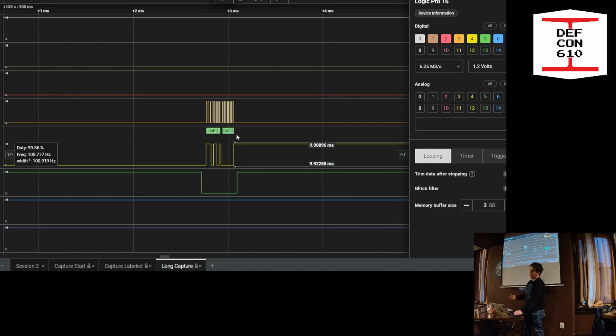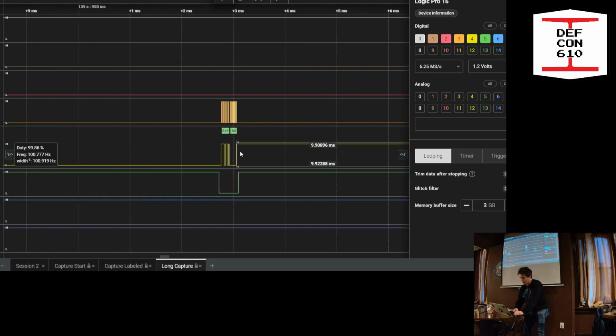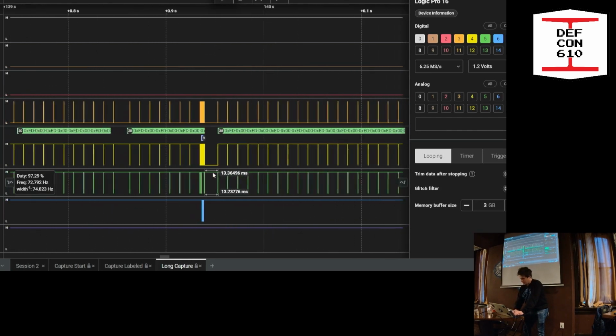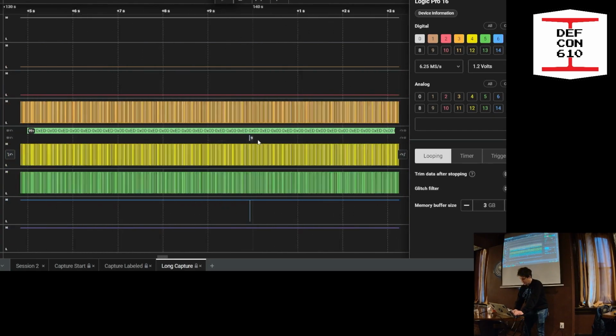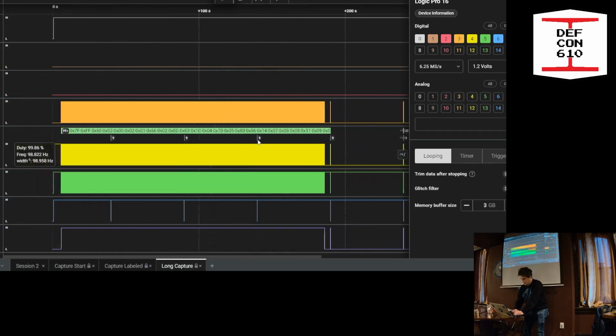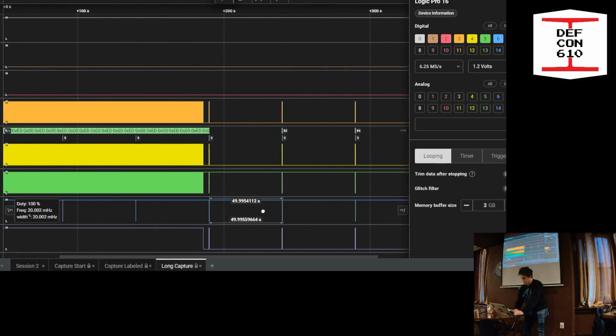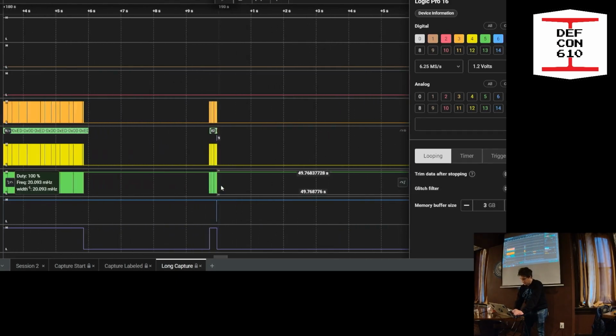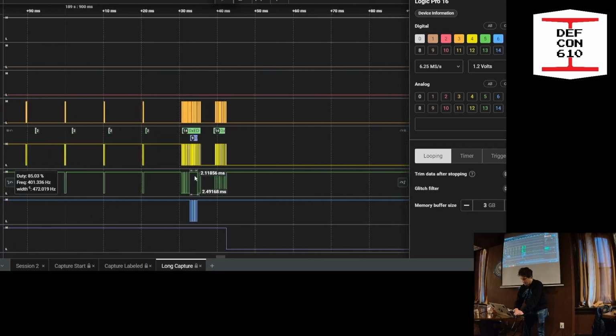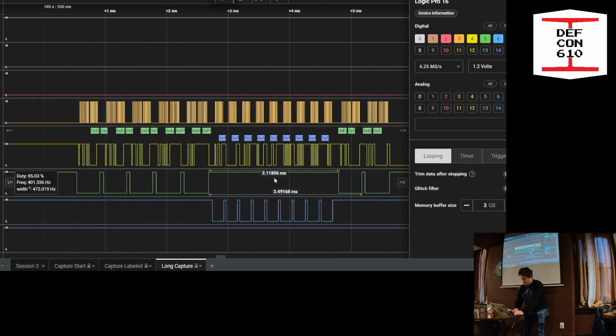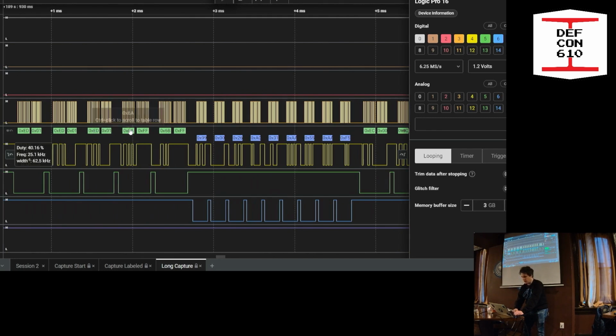So we can assume that ED is a register that it calls to say, hey, there's data available, please get the data. So if we go to the next one, we can see with the interval, so about every single 50 seconds is when it sends data. So we can zoom in at any point. And then we see the same sequence, ED01, 6AFF, 6BFF, and then the data.